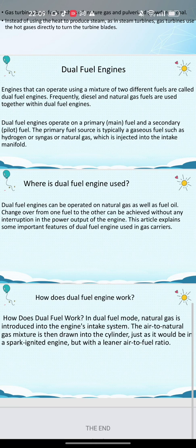Disadvantages of dual fuel engines. Dual fuel conversions suffer from major increases in carbon monoxide or CO and hydrocarbon or HC emissions and loss of fuel efficiency at light loads. This is because they operate unthrottled, so that the air fuel mixture becomes leaner as the load is reduced.